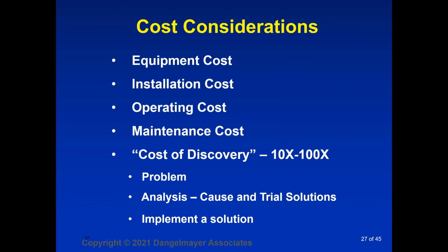And when you're installing ionizers with heaters, you need to be concerned about providing power to them all. An ionizer that uses 2 to 10 watts of power, you never really are concerned about. But when an ionizer starts using 300 watts or more of power, then you need to be concerned about how many ionizers you're installing and whether you have the power capabilities to power them.